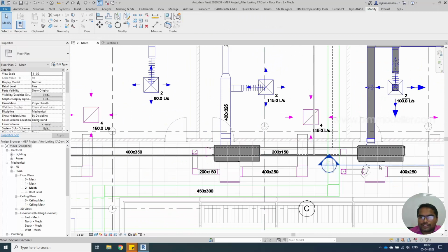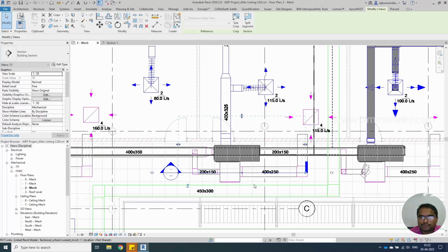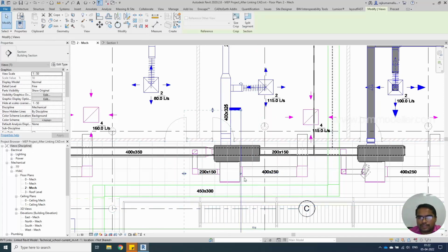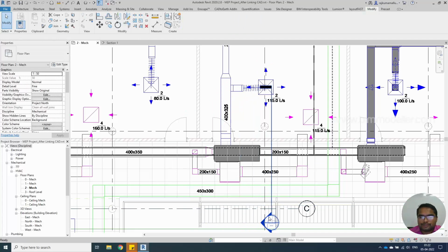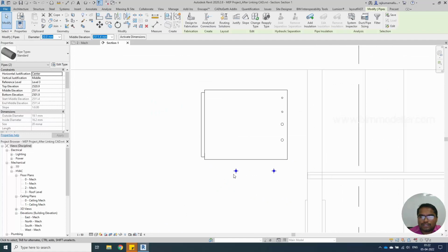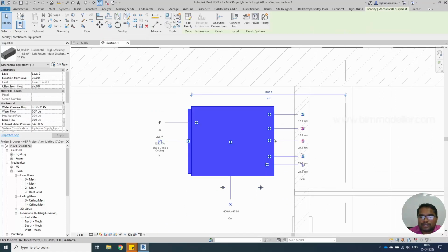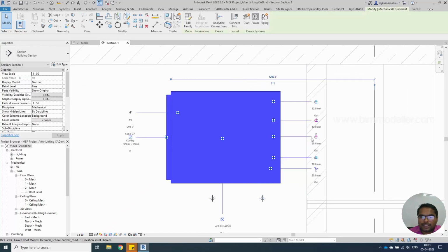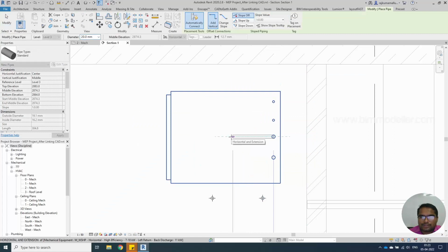You have to move your section view from that place to here. Rotate the section view like the previous time, 90 degrees. Move it nearby. And you will be able to see your pipe which goes through your section view, and we have our connections in this place. Select the pipe, draw the pipes. Make sure it aligns with the center line like this and connect with the pipe.